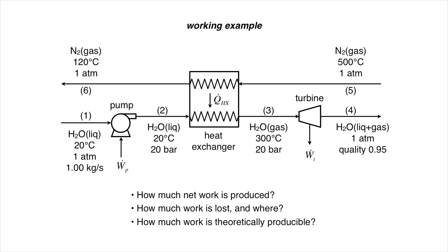One thing you'll notice right away is that this isn't a heat engine with a high and low temperature reservoir. So the Carnot ratio, 1 minus Tc over Th, even if we could decide what Th and Tc are in this problem, is not really a meaningful benchmark. Also, this process doesn't involve any heat flows in or out of the process, or even among the various units. Although there's thermal energy transfer Q dot Hx inside, the heat exchanger as a whole is adiabatic, since if we draw a control volume around it, only material is flowing in and out, not heat. So we need to rethink how we perform a second law analysis for an open system like this.